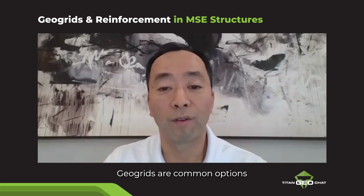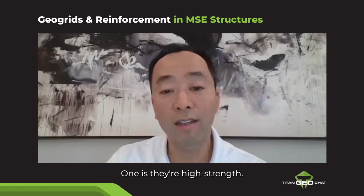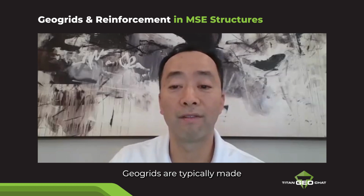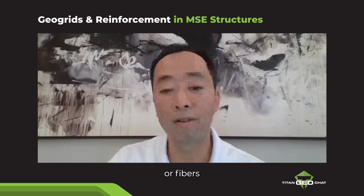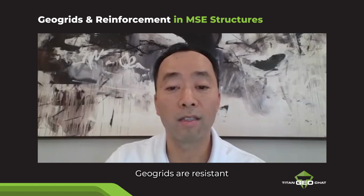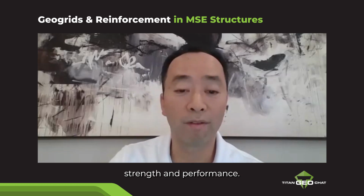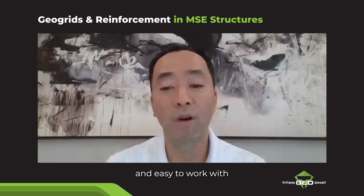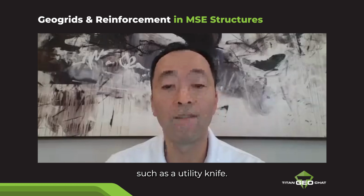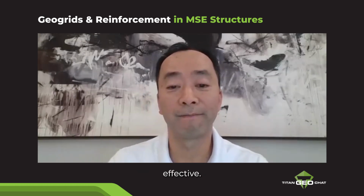Geogrids are common options for the reinforcing element for mechanically stabilized earth systems for several reasons. One is their high strength. Geogrids are typically made of high strength polymers or fibers that can provide a strong and durable reinforcement. Geogrids are resistant to alkaline soils and are UV resistant, which ensures strength and performance. They're flexible and easy to work with and can be cut with a simple tool such as a utility knife. And finally, geogrids are cost effective.